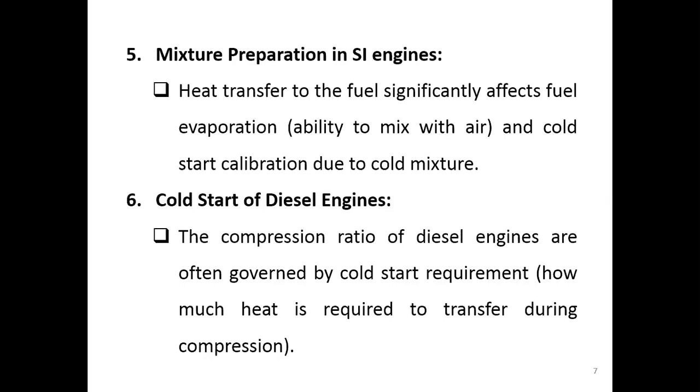If you start it in winter seasons, some of the heat that comes out from compression may go out to the surroundings, not all of it goes into your cylinder. So you will have a problem starting this engine because of this.